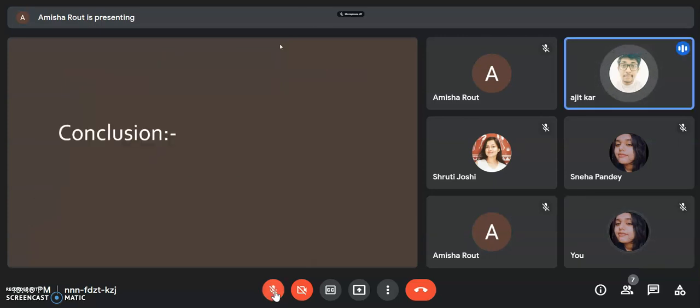Thank you. Let's get to the conclusion. As to the control of material flow by use of textures, in drawing tests it is shown that the friction can be influenced by the use of rolled textures. So by transferring these, the material flow is retarded in desired areas.